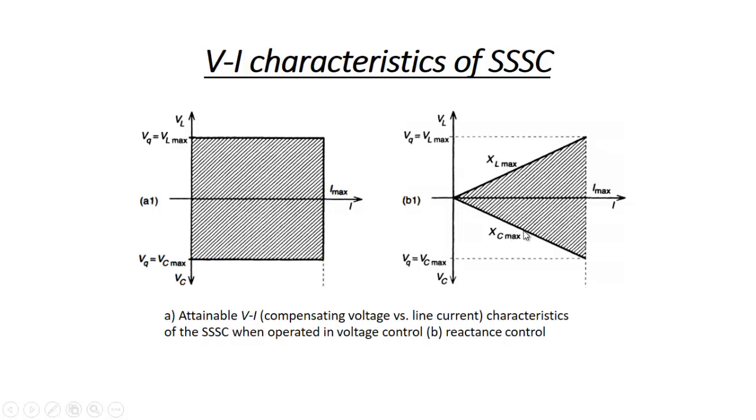So in case of TCSC, we have actually the same sort of control. In this case, we have some impedance limit from this point to this point, otherwise the voltage control would have been same because of that resonance. So to avoid that resonance, we have to avoid that range, that is alpha L minimum to alpha C minimum.